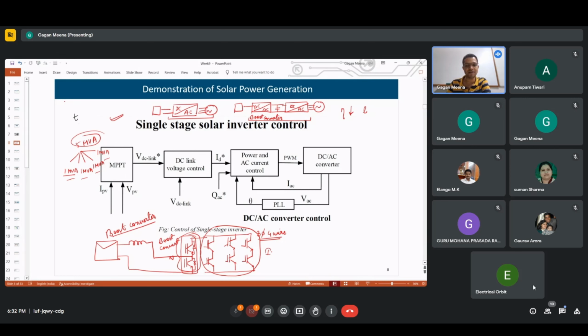The next one is the fourth, which is DC. All three of these are AC. This is the DC fast charger, mode 4. All EVs charge in DC only, because the battery takes DC power. But why are we using AC? Why do we need AC chargers? Anyone? And if we can have DC chargers directly, why not have this DC fast charger on the vehicle itself?